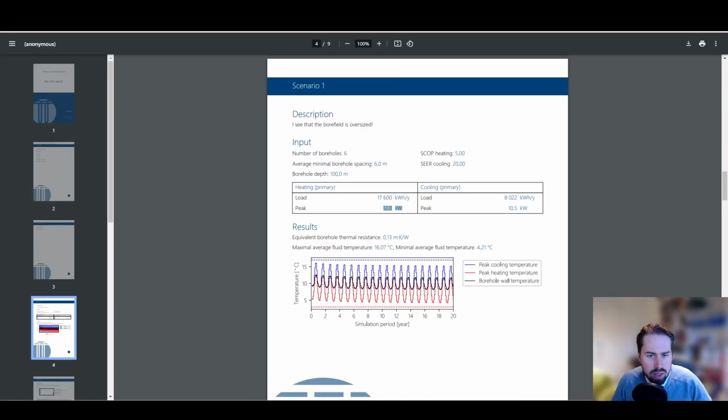And the reason why we've done that, perhaps we will add the function in the future to also have it as a secondary load, but it's to have the most transparent way to communicate about the geothermal load, because the way you size your bore field is not depending so much on the heat pump that you installed, but on what exactly is coming from the ground.